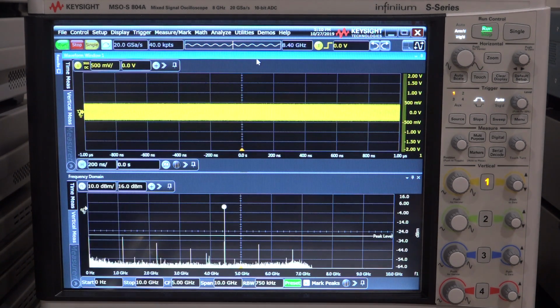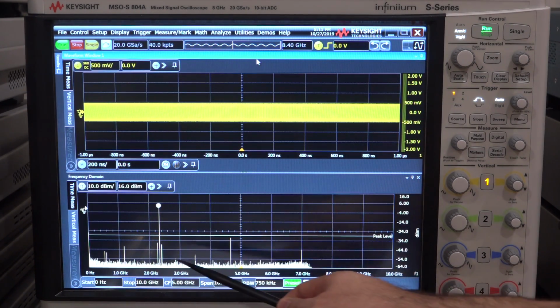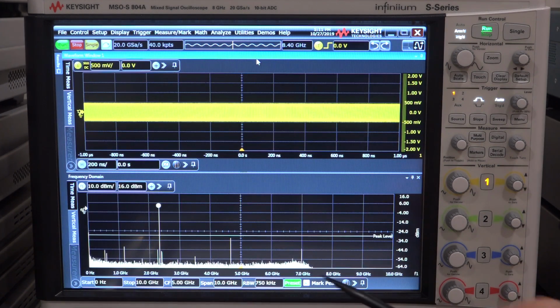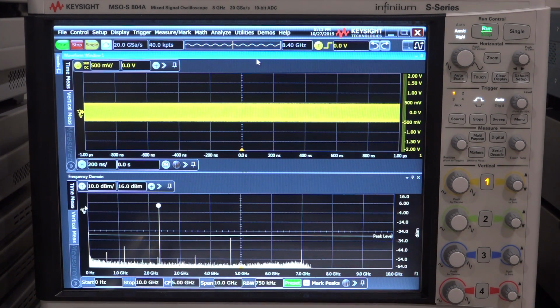So we're going right now at 4.15 gigahertz. Keep going. There you go. You can see this VCO switched all the way down here. Some additional tone on the side. Here's a second harmonic. Now the VCO is a fourth of this frequency. So it still works. And I can go up higher and keep going. You can see it's still tracking. The second harmonic is growing a little bit there.